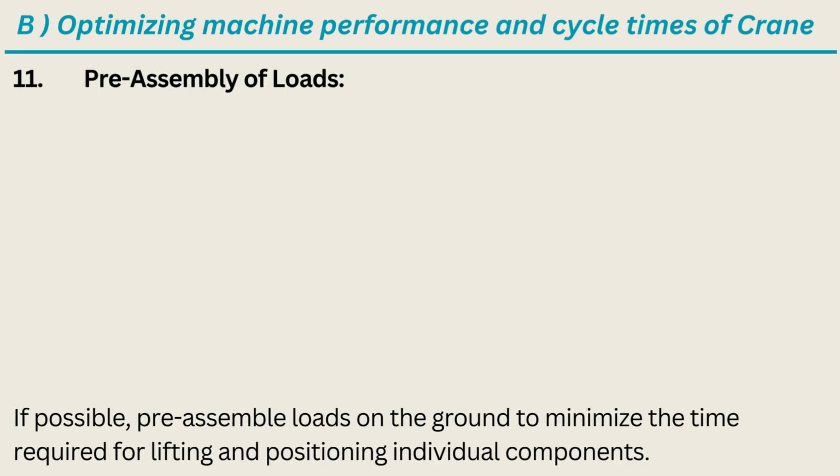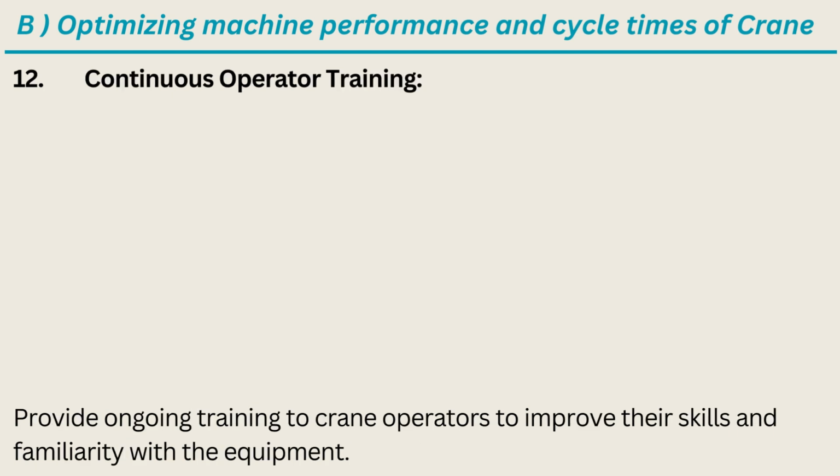11. Pre-assembly of loads. If possible, pre-assemble loads on the ground to minimize the time required for lifting and positioning individual components. 12. Continuous operator training. Provide ongoing training to crane operators to improve their skills and familiarity with the equipment.